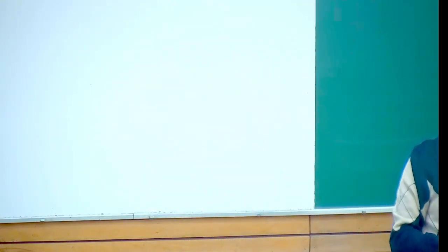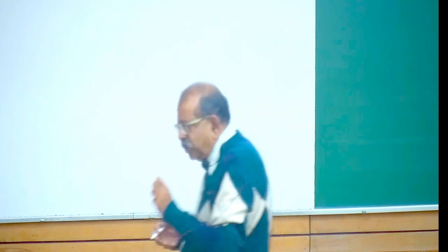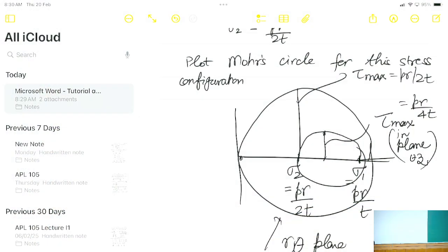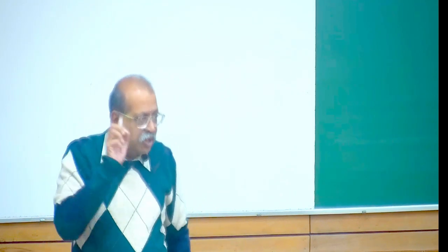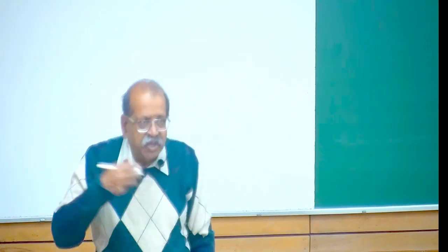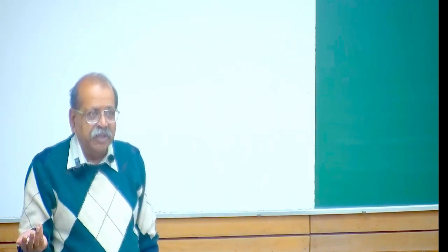And this is an example of how, in a 3D problem, we use Mohr circle. We can only do Mohr circle for principal stresses in 3D problems. If taus are given, we cannot use Mohr circle for the 3D problem. So we locate the 3 principal stresses. In this case, luckily, we are able to do it easily.